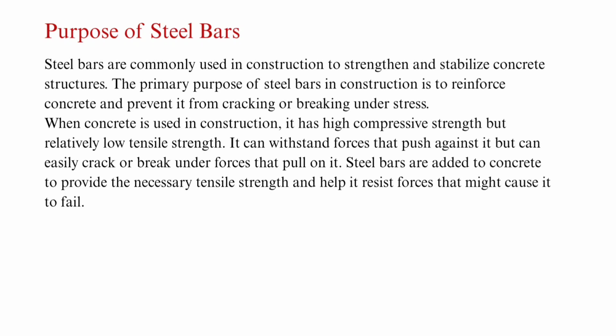So it can withstand forces that push against it but can easily crack or break under forces that pull on it. So steel bars are added to concrete to provide the necessary tensile strength and help it resist the forces that might cause it to fail. This is the primary purpose of using steel bars as reinforcement.